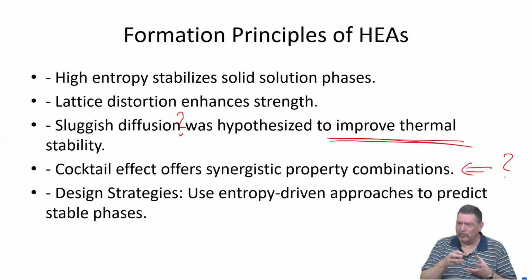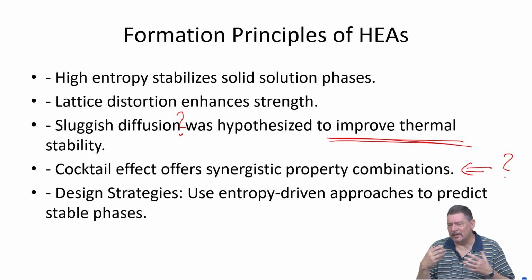But if you now mix it, then it might turn out that because of bringing 5 constituents together, having all the lattice distortions, and associated with them different electron configurations in the local bindings between all the constituents, there might be a shift in the effective electronic structure such that ferromagnetism could occur. This would be a cocktail effect.